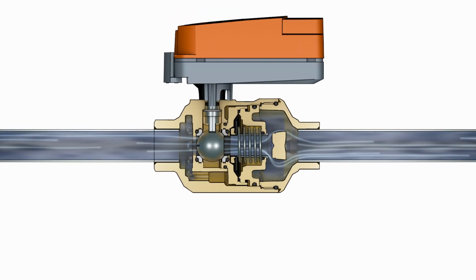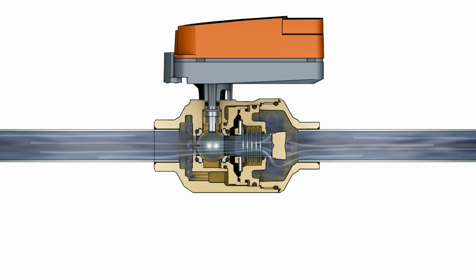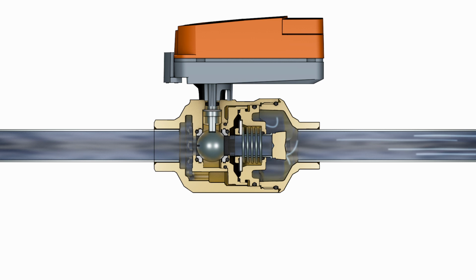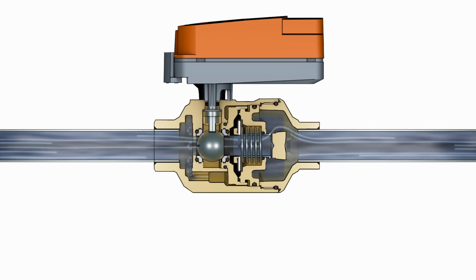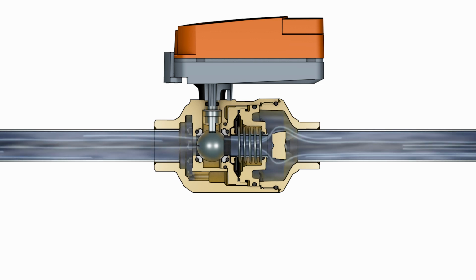As pressure increases, either from the pumps or from other control valves closing, the diaphragm is forced back against the spring, closing the available orifice for water to enter the valve. Equally, as pressure is decreasing, the spring forces the diaphragm back, increasing the surface area available for water to enter the valve. The result is a constant pressure to the back of our control valve. So now, any known position of the valve equates to a known flow rate.